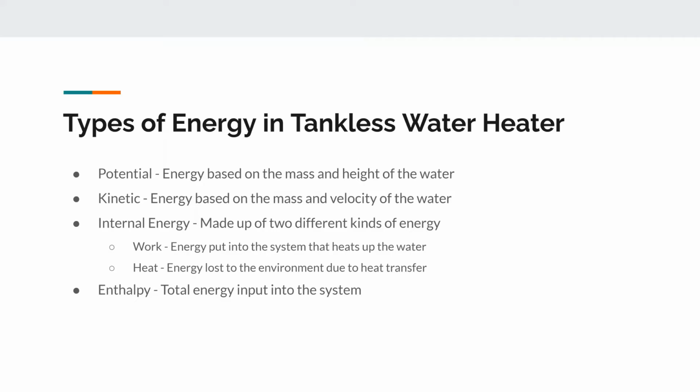The same can be said about the kinetic energy. Water is moving throughout the water heater with velocity. However, the velocity is constant throughout, meaning it enters and leaves with the same velocity, and so the kinetic energy change is also not present.